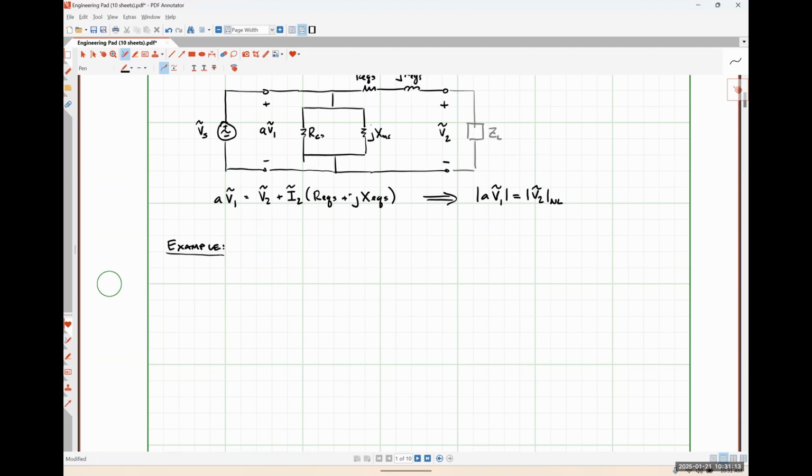So here in Ruston, if I am not mistaken, the voltage that we would see in the transmission lines throughout the city is, I believe, 13.5 kilovolts RMS. And then that is getting stepped down to 240 volts RMS for any single phase consumers like homes, and it's getting stepped down to 208 phase to phase or 120 phase to neutral for apartment complexes and things like that that utilize a three-phase system.